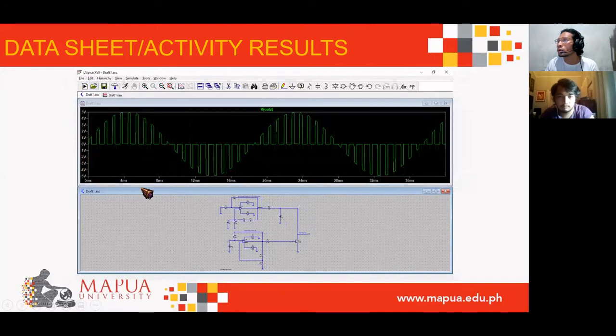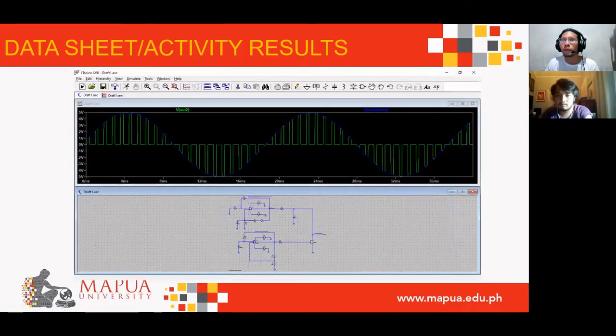So next is the output or the pulse amplitude modulation signal, where the inputs, such as the sine wave or modulating signal and the pulse or square wave signal, are multiplied in the pulse modulator circuit, and the amplitude of the carrier pulse train is varied using the amplitude of the modulating or the message signal.